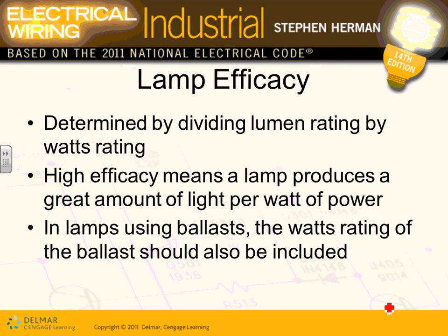Lamp efficacy. Yesterday you did a comp check for us. The single most important reason we do a comp check is that we need to make sure that we are efficient. We don't want to burn more energy than we need to. So the way they do it, guys, they take the lumens divided by the watts, lumens per watt. The higher the lumens per watt of the fixture, the more efficient the fixture is.